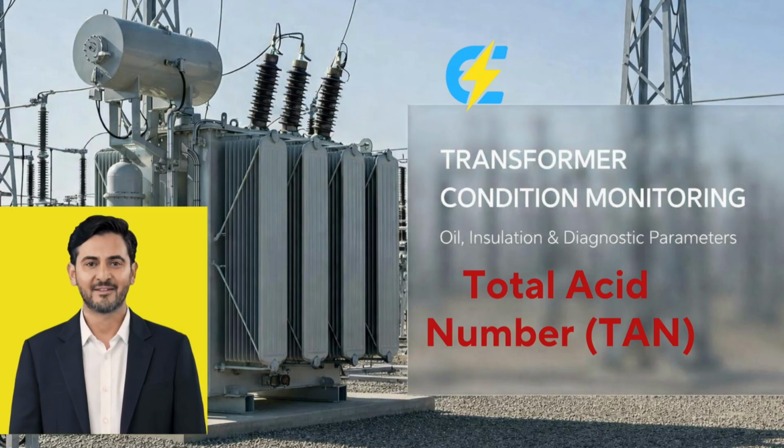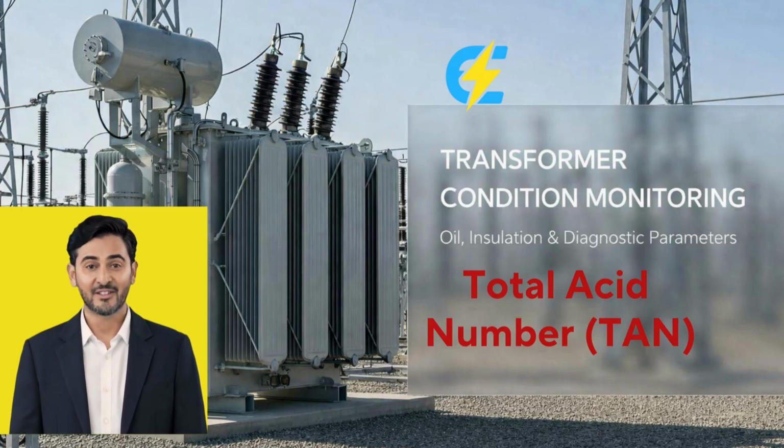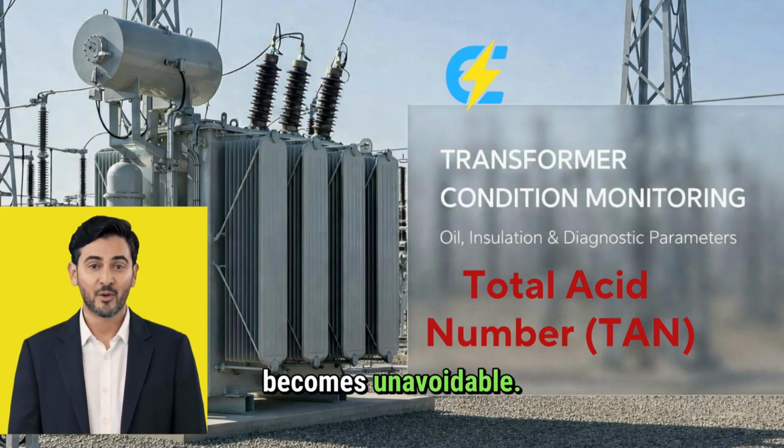Rising TAN, accelerating aging. High TAN, insulation life loss. Unlike gases, TAN never goes down on its own. If TAN is rising, monitor closely, control temperature and moisture, and plan corrective action. If TAN crosses critical limits, oil reclamation, or oil replacement, becomes unavoidable.